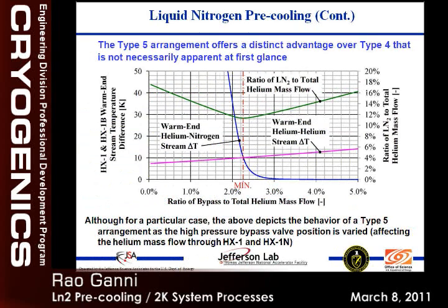Now when we go back to splitting the helium into two stream heat exchangers, we can see how, based on the unbalance, there is a minimum of nitrogen consumption. On either side it is more than the optimum. To control the nitrogen, most of the time they use the nitrogen vent temperature, which they think of as the polarity to control. Actually, the nitrogen consumption is less sensitive to the nitrogen vent temperature than to the temperature difference on the helium to helium heat exchanger. So basically, the helium to helium heat exchanger temperature difference is the one direct indication of how much nitrogen you use, compared to the nitrogen vent temperature, which is a huge shock, very hard to control, and doesn't really reflect the minimum.